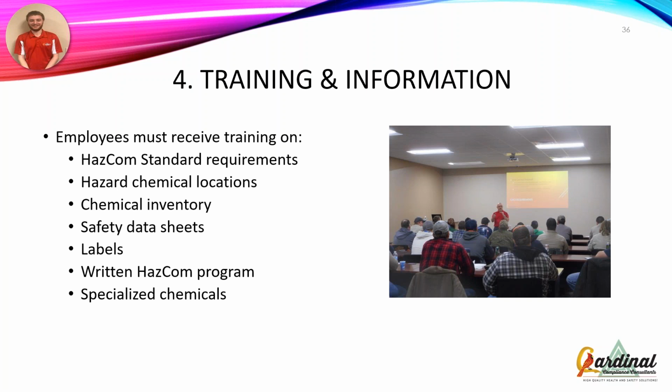We also need to train them on those safety data sheets and the new labeling, because your workers are the ones who are receiving that information in, and they need to be able to look out for it when they're receiving something at the shipping dock or what have you. They need to make sure that everything has those proper labels and comes with that safety data sheet. Then you have your written HAZCOM program. Your employees need to know the elements of that, which we're going to talk about here in just a moment, but you'll need to train those employees on that as well. And any specialized chemicals you might have, like I said, temperature controlled or things that are reactive with water or air would definitely be a great area to hit with your employees so they know what they're dealing with.